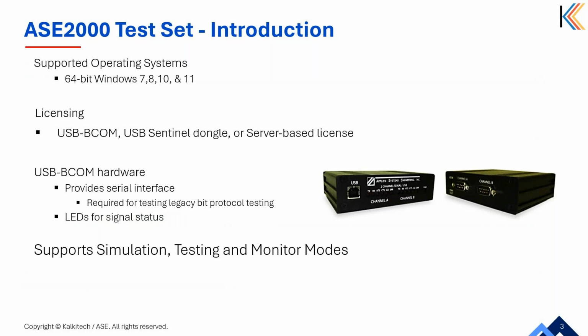Modes of operation that we support are master simulation, RTU simulation, or field side device simulation, as well as bidirectional monitoring of the communications to and from the master and those outstations. The test set was originally deployed in the late 80s, early 90s, and several enhancements have been made since then.